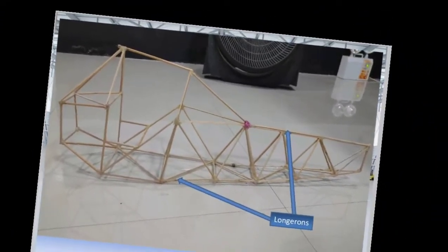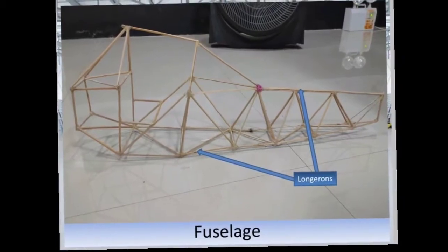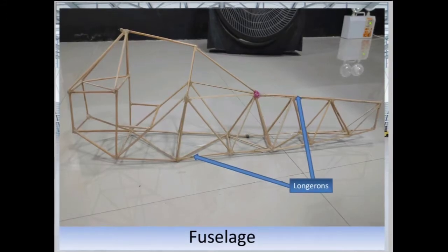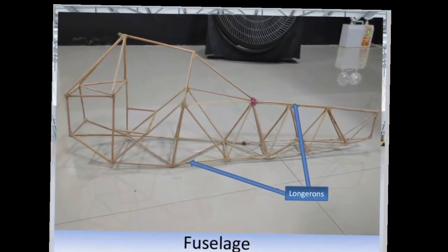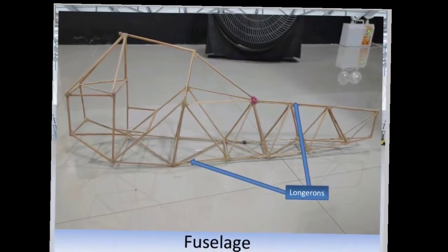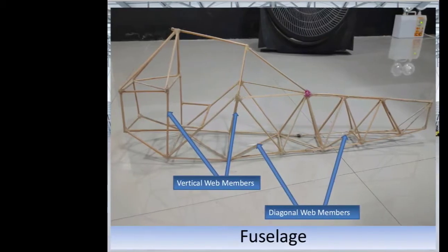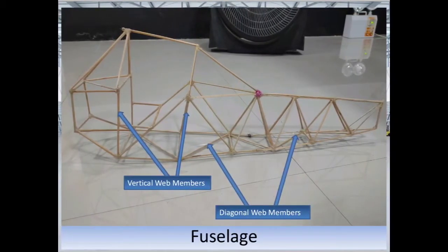Longerons are spar-like structures that run lengthwise of the airplane's fuselage or spanwise of a wing. The purpose they serve is to transfer loads and stresses from the aircraft's skin to the formers. The diagonal and vertical web members are riveted or bolted into one piece with cross-bracing members. Small airplanes generally utilize these web members using aluminum alloy tubing, which are used to reduce the weight of the aircraft.